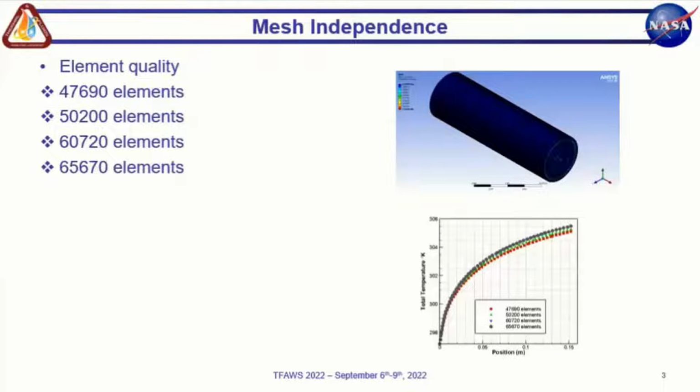The one approach is to use a single phase model and assume that you just have one fluid and it has the appropriate properties, by doing some sort of weighted average combination of properties of water and the aluminum oxide, and then treat your fluid as a single phase fluid with these new calculated properties.